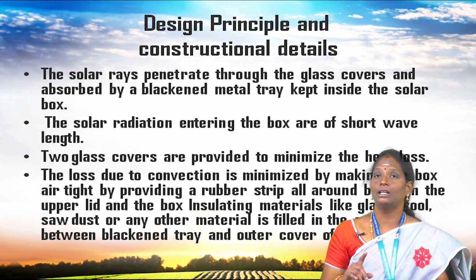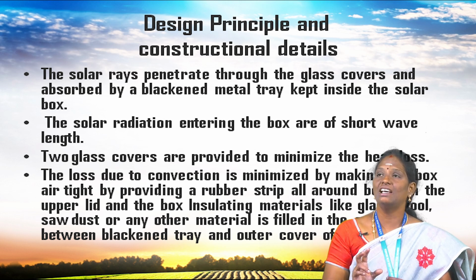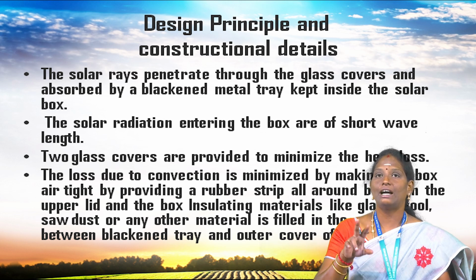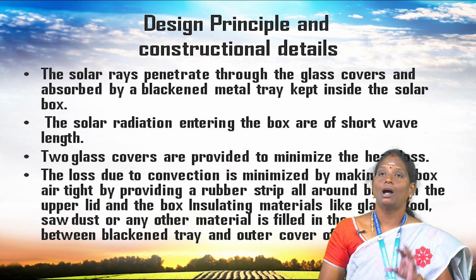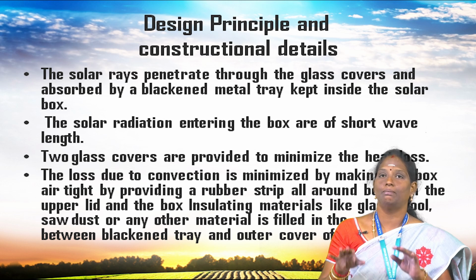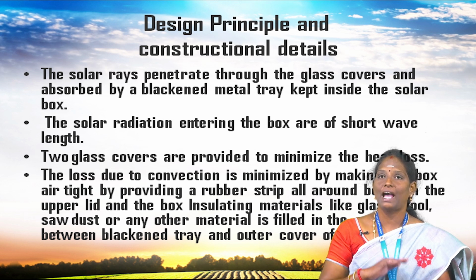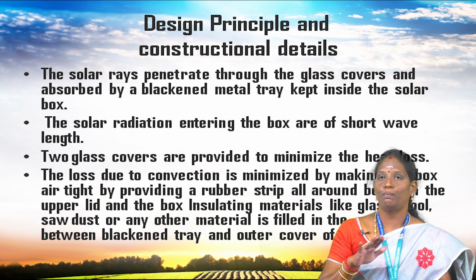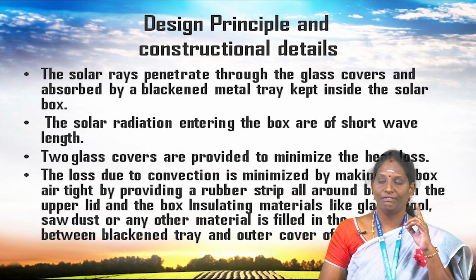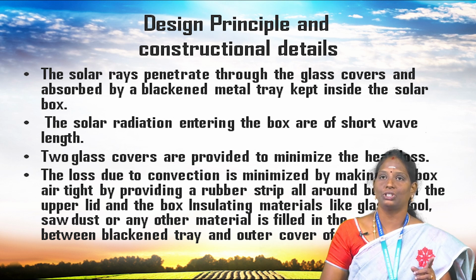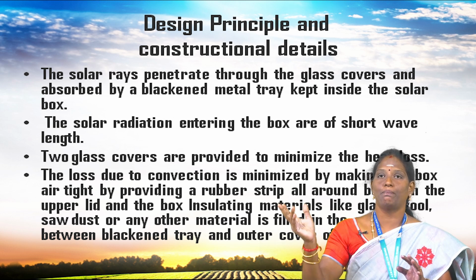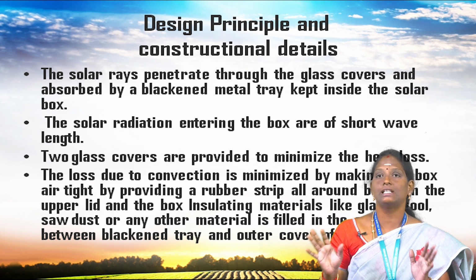The solar cooker is made up of inner and outer metal or wooden boxes with a double glass sheet on it. The absorber tray or blackened tray is painted black with a suitable black paint like blackboard paint. This paint is dull in color and can withstand the maximum temperature attained inside the cooker as well as water vapor coming out of the utensils.